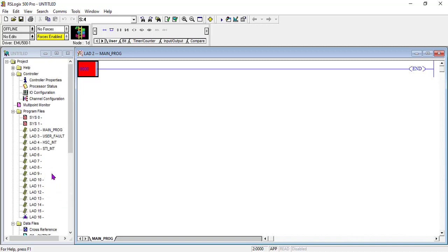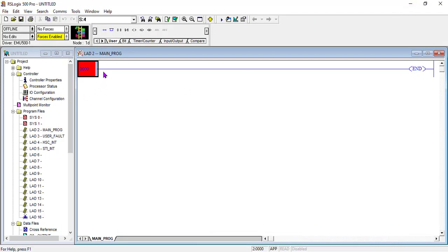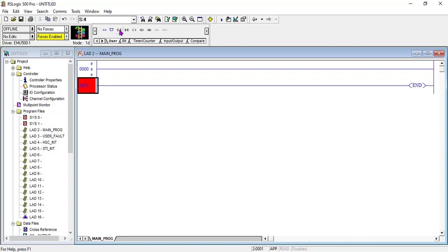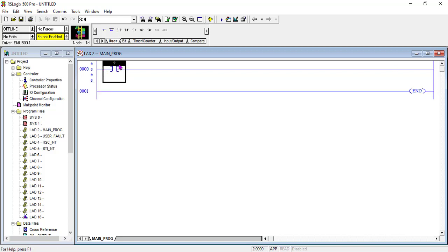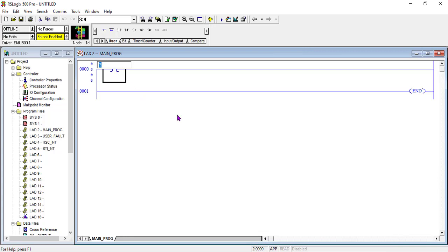So let's look at what we wrote before. Let us practice. Let's look at how one achieves this. Let me add a rung. Okay, I've added a rung. Good. So I take one NO. I need an address. There is always an address. Remember that we see in this place, here you saw I/0. That's an address. I/1 is an address. So this address cannot be 2, it's always 1.